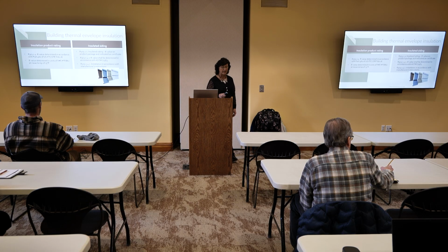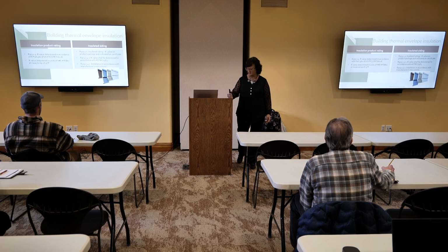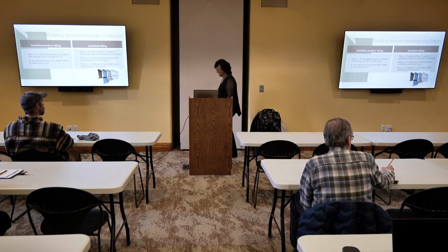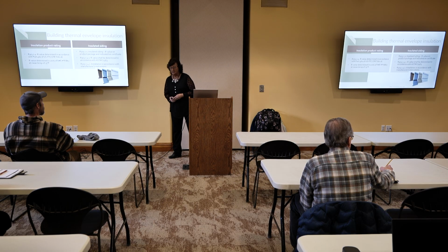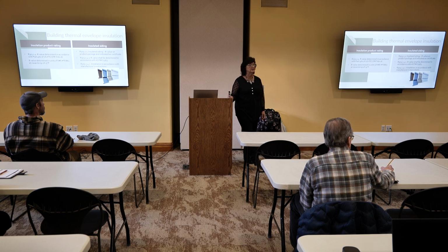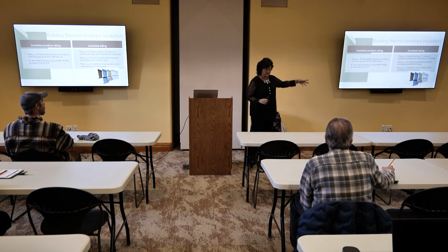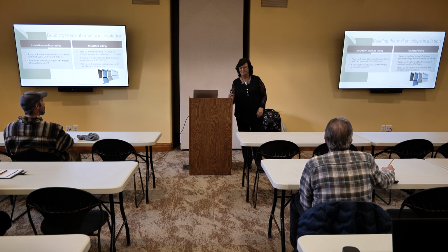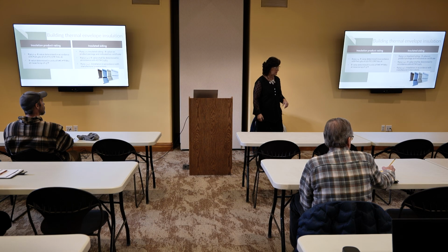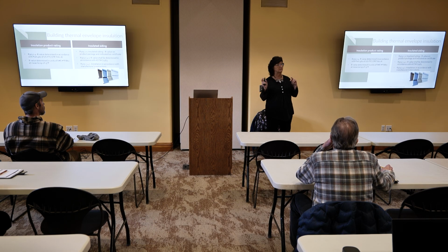For many code cycles, Matt Dobson, the vinyl siding guy, and I fought at the code hearings because I didn't think vinyl siding, insulated vinyl siding, should be allowed to be considered continuous insulation, just because there's a lot of things about it, the way it's installed, the air movement, the different levels of insulation, that it shouldn't be considered that. However, in the 2024, it made it into the code as a continuous insulation with some caveats.